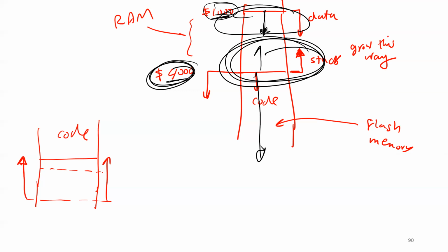But I want to tell you something here, because this is a very basic computer. We don't have an operating system. So it's your responsibility to manage the memory. Otherwise, your program is going to crash. This means you have to make sure you are not going to use too much stack. You have to make sure you have enough space for data and enough space for stack, so they are not going to overwrite each other.